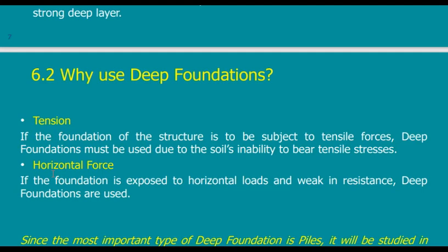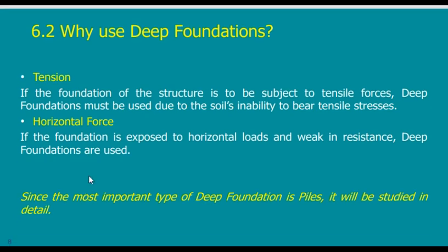With small horizontal load, the friction that we have studied before, the friction between the footing and the soil, will be adequate. But if the load is high, then this horizontal load will need piles to be used. So it is tension or horizontal load. If you have tension or horizontal load, then you should go to piles or deep foundation.